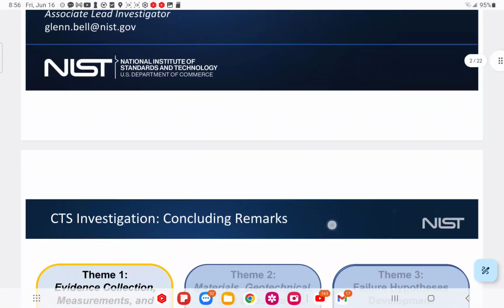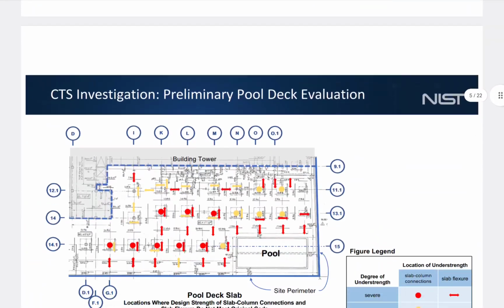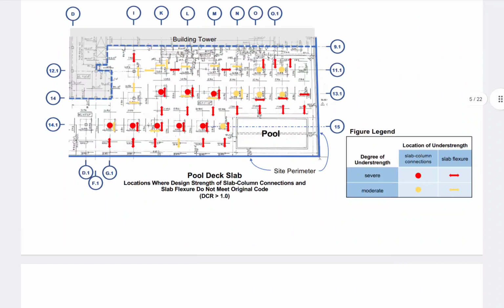This is something that a student would just be guesstimating at. This is shit. All right? This is not talking about, they had a chance here to add the original load path. This is nothing. This is something that we see in a photograph that they just now put in a drawing and made their little dots and arrows. All right? The stresses are all 90 degrees to each other. That's bullshit. The stresses are not all 90 degrees to each other. There is a rectangular array issue going on, a torque issue going on. That's how we get to this K1 issue.